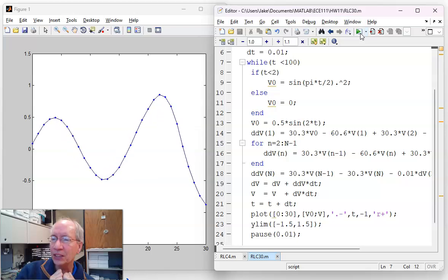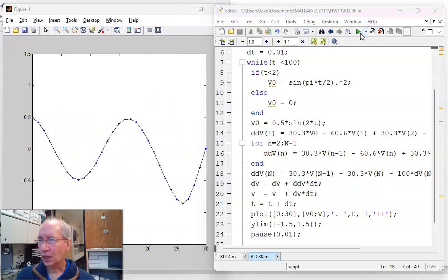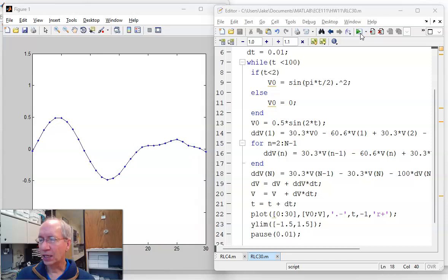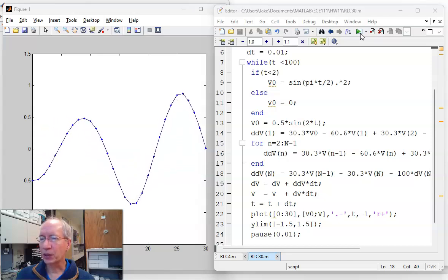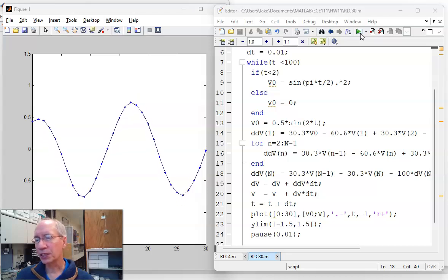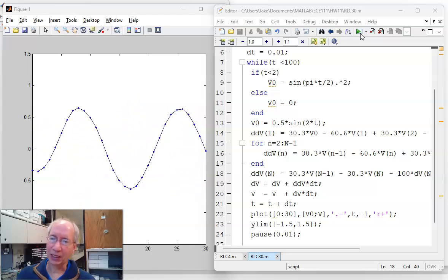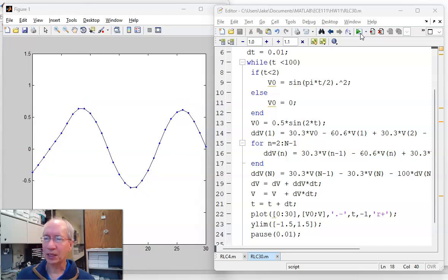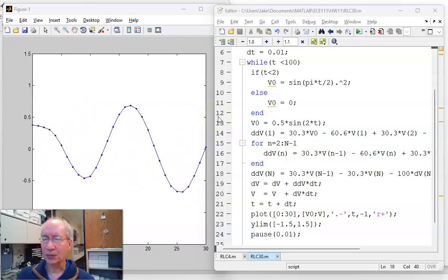So here you can kind of see the standing waves forming. If this number is too big, I get the same problem. Now the right endpoint barely moves. That causes negative reflections. The negative reflection and the plus waveform coming in start creating standing waves. Again, that can cause trouble.